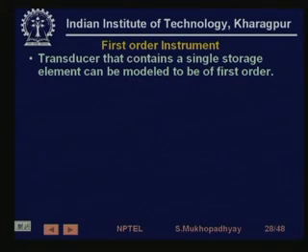So even if you suddenly fill this space with, let us say, steam, the temperature of the junction of the thermocouple will not instantaneously be equal to the temperature of the steam, but it will slowly rise, right. So for such transducers, we have a first order instrument character, first order or second order. That will depend on the modeling of the thermocouple.